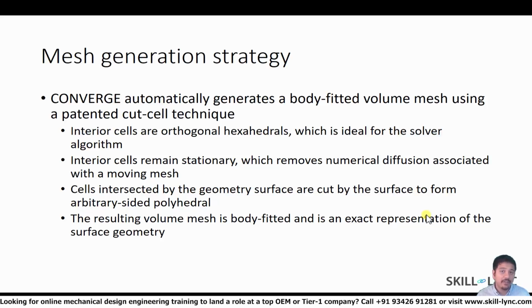Well, you might have heard of different types of meshes like tetrahedral meshes, polygonal meshes, and so on. Out of all these types of meshes, your Cartesian mesh or hexahedral mesh is going to be ideal for the solver. It reduces the errors in your discretized equations, meaning with just a small number of cells you will be able to get the right answers.